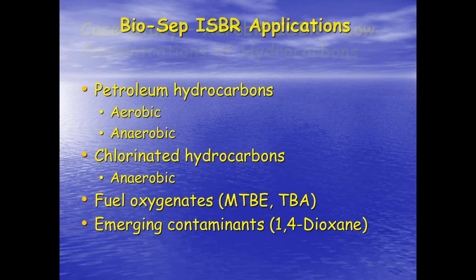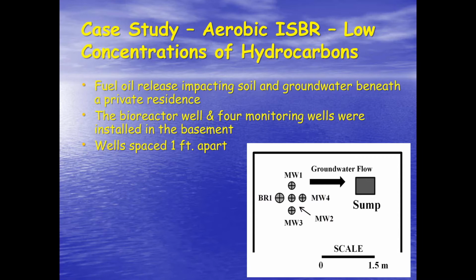Now, I want to show you a couple of case studies. I don't have time to show you a complete set of case studies, but I'll also refer to that at the end of the talk so that you can get copies of the additional case studies as well. But the first one I want to talk about is an application of the Aerobic ISBR in a situation with low concentrations of hydrocarbons. This in particular was a fuel oil release that was impacting soil and groundwater below a private residence. And we installed a 2-inch monitoring well here where the in situ bioreactor was going to be deployed.